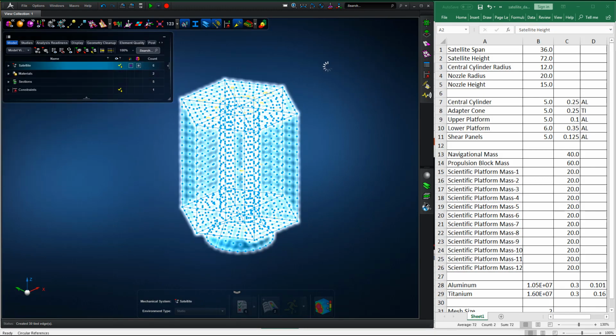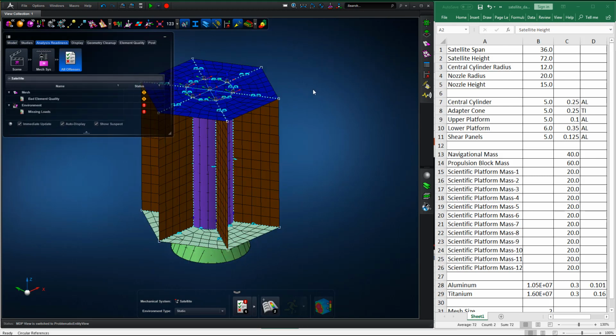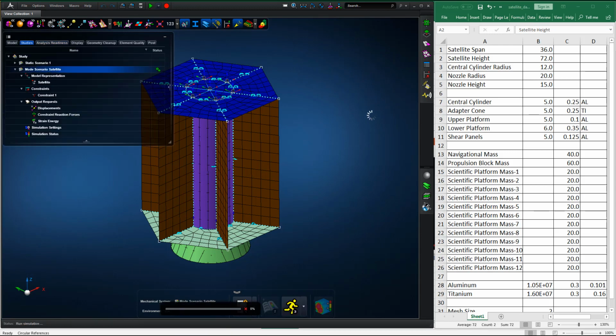And we can see this is the second set of parameters used to define that level of geometry. We can now place an analysis scene and run a normal modes analysis on this structure. We can start to see how the use of Python scripting in terms of parameterizing models, again very quick and easy, is starting to form the basis of a manual or even an automated optimization routine, coupling in some of the different optimization techniques that are out there, evolutionary algorithms, that type of thing.